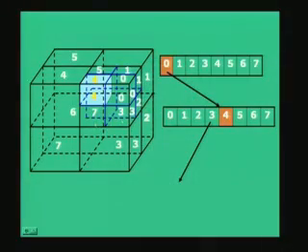As you look here on the slide, I repeat again with a simple example of only about 2 levels of decomposition at the most, that if a solid occupies a part of 4 or even the full part of this sub volume 4 at the second level of decomposition, we will say that unit will be labeled and it will be set to 1. All other units in the first level of decomposition and the 7 of them at the second level of decomposition, if there are no solids occupying that particular space, we will set to null.